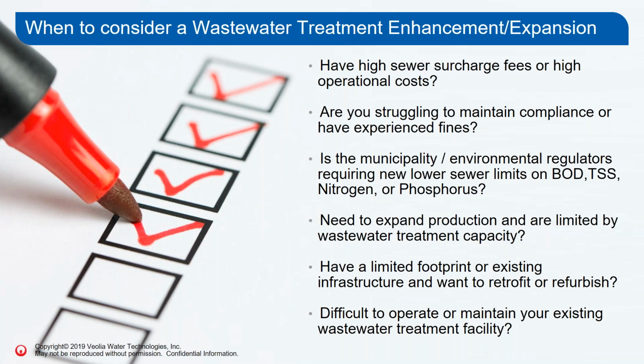So basically, if you have a wastewater treatment plant, and I'm assuming most of you in the industry already have wastewater treatment plants, it is about how we are going to expand or enhance the treatment. Some of the factors to consider: if you're paying high sewer surcharges or have high operating costs for the treatment, this can be a driver for you to consider upgrading a facility.